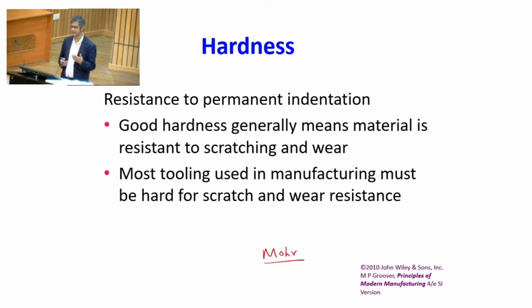Okay, this indicates resistance to wear, plastic deformation, even scratching. You know the Mohs scale, right? That's where scratching can be used to measure hardness. In the Mohs scale, diamond has the highest hardness, talc has the lowest hardness. In between, you have 10 different materials present.